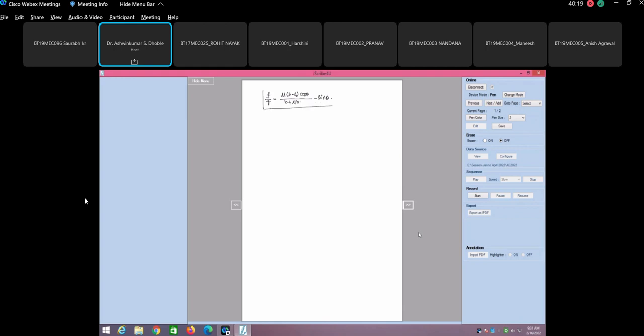So this you get the expression for the deceleration, and then for the rear force, sir, you will get B minus L cos theta divided by B plus mu H into W, and RF is equal to W cos of theta minus of B minus L cos of theta divided by B plus mu H, whole thing multiplied by W. If you simplify this, sir, you will get L plus mu H divided by B plus mu H cos of theta into W.